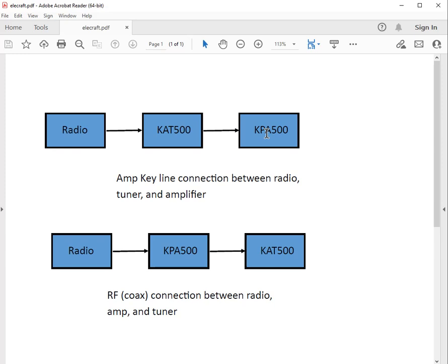So a high SWR condition is probably the most common, and it will interrupt the key line, and of course if the amplifier faults, it'll stop transmitting. So I believe we can cause both here, and if I don't get carried away with it, it shouldn't hurt anything.